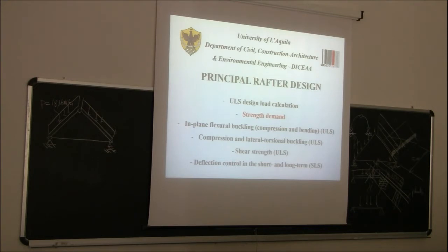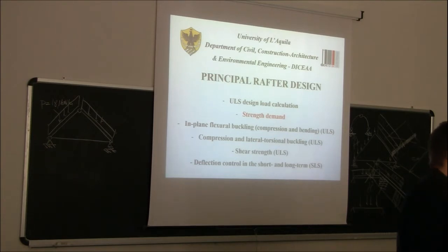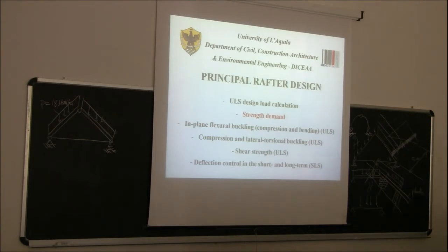Nine, my goodness. So it means that now we need to write 9 congruence equations. I wouldn't do so. This you can do with the professor. Too complex, I wouldn't be able to do it. 3 is also complex. I would struggle to write 3. 2. Now we're going down, of course. It becomes easier and easier. Can we get to 0 possibly? Because with 0, I write the 3 equilibrium equations without any congruence, and that's something that I can handle.